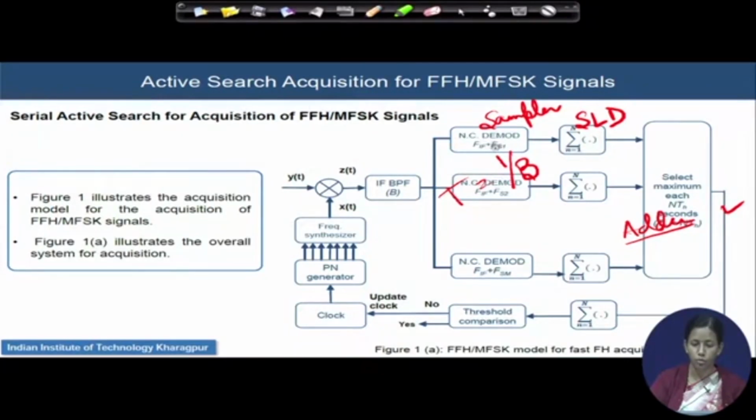So, you put all of them in parallel, that is why we have put so many demodulators and detectors here in the receiver path, and all the parallel inputs are checked all the time, each creating some output. Out of all this, with whom the input will be perfectly synchronized, nobody knows, but once it is synchronized, the output of that typical demodulator will be higher.